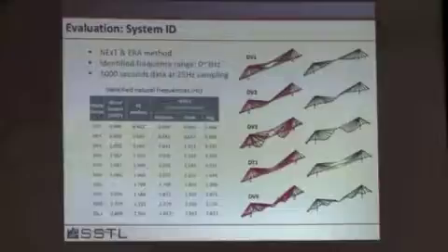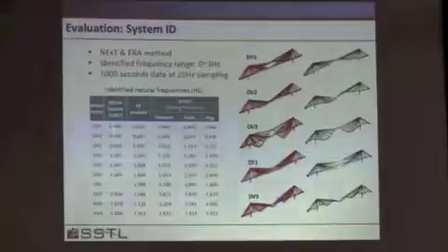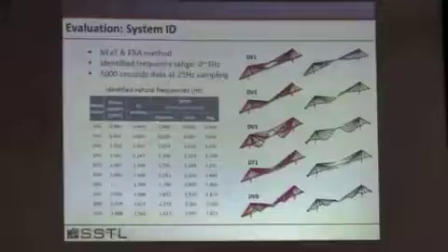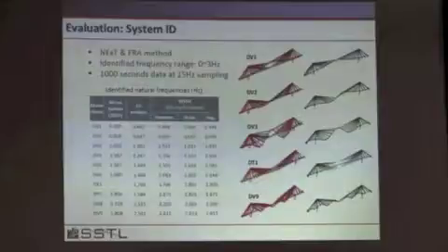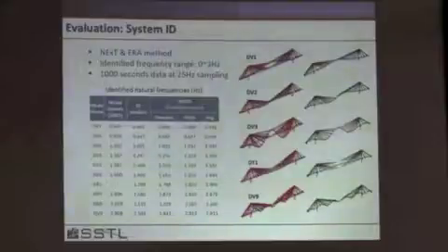And what you see is that even for these higher frequency modes, the modal survey of the wired system and the wireless system, this was not during a typhoon, the frequencies are quite consistent. And they're also quite consistent with our model. So what does that tell you? That says that even though this typhoon came through, it really wasn't a big event for this particular bridge. We're still in the linear range with the response by and large. We still have very clear mode shapes. And so this typhoon was not a challenge for this bridge to undergo.